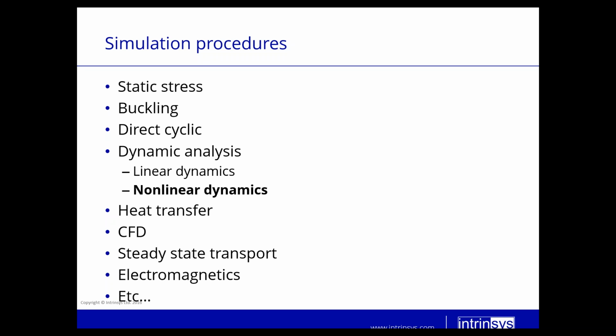Heat transfer is slightly different from the previous ones. Instead of solving for structural deformations and stresses, we solve for temperatures and heat fluxes within the part. So heat transfer does not take any deformation into account. Now in Abaqus you have various options to combine the heat transfer simulation with a structure simulation, in which case you can get the combined effects of